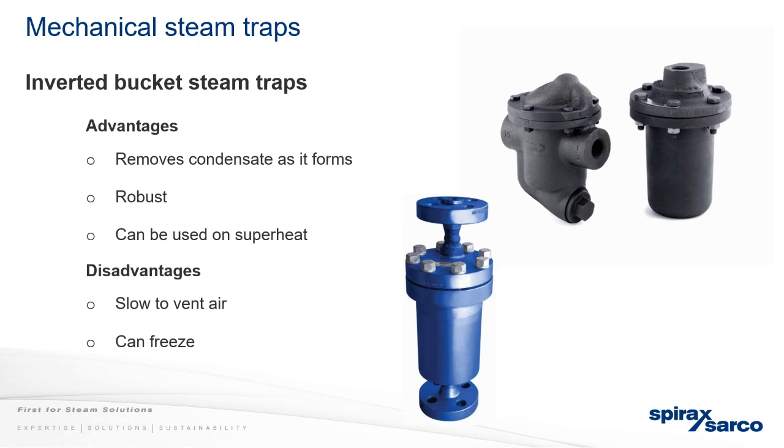They are open to air binding at times, and they can freeze. I've seen it in the UK and Europe. It doesn't do too much damage to the trap once it's defrosted.